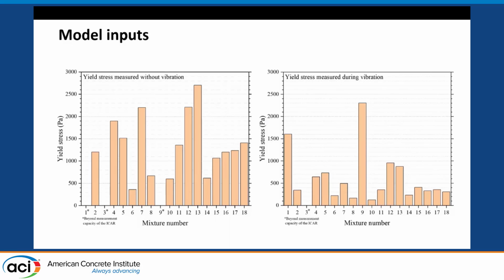So I'm just showing some of my inputs here. So yield stress with vibration, without vibration. I also collected information about viscosity, what the density of the mix was, what the slump of the mix was, etc. But I'm only going to show yield stress today.